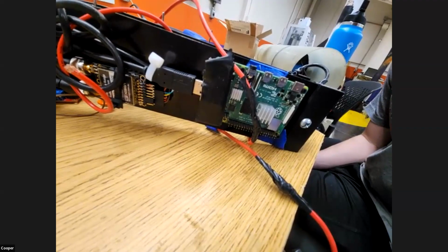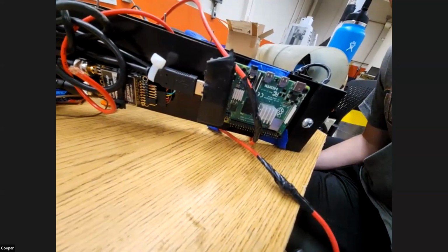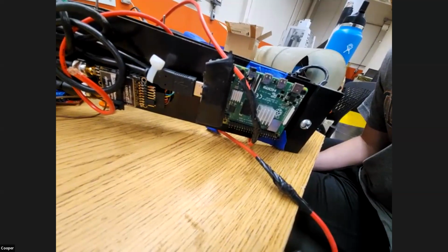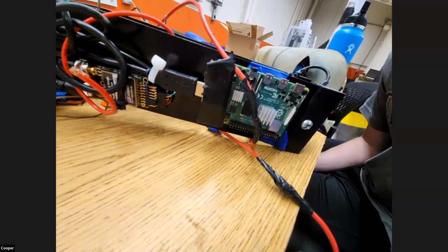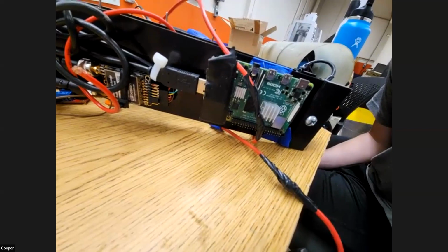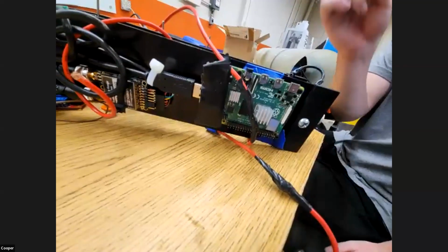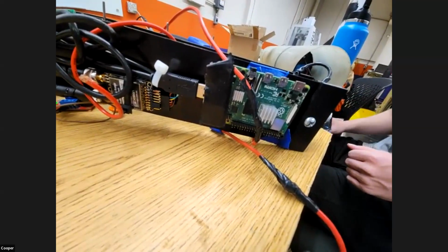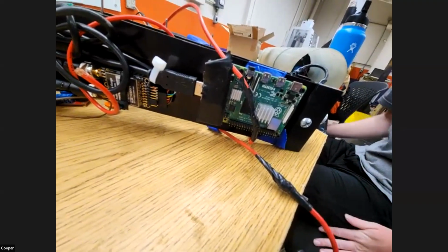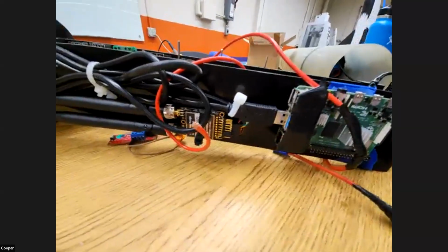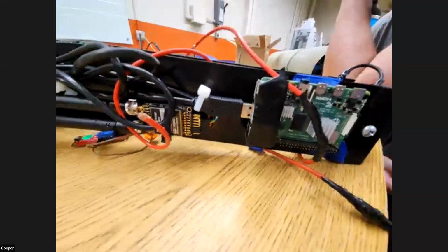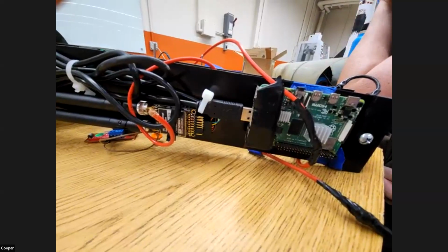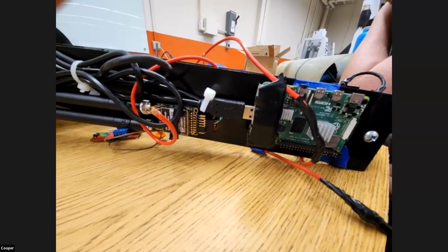That USB connection to the Raspberry Pi is probably one of the strongest ones the Pi has, but it could still potentially come loose in a bad scenario. So you want to secure all those down. I use lots of hot glue and zip ties just to make sure that everything is out of the way. But also keep in mind, you're going to be asked to pull that thing out of your rocket probably several times during range safety inspections.